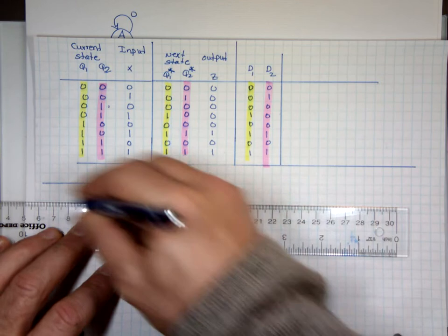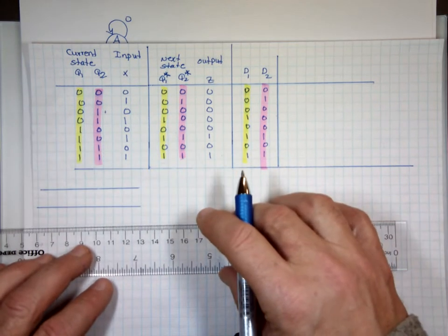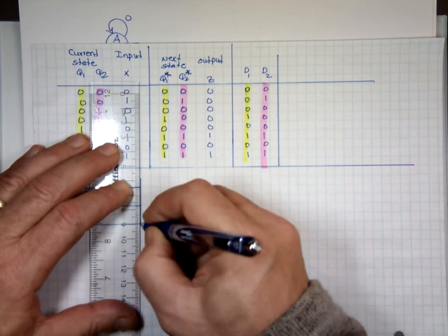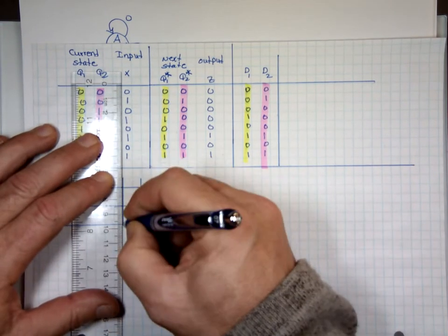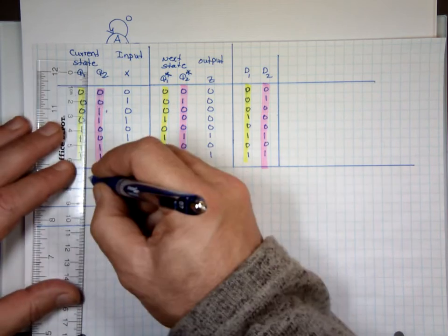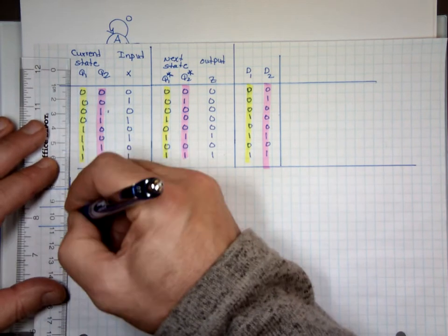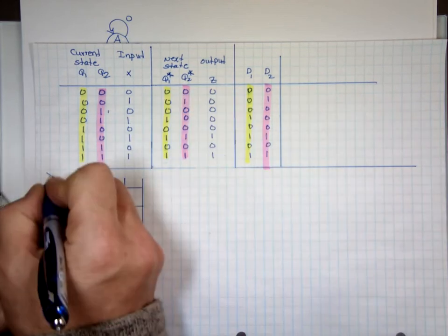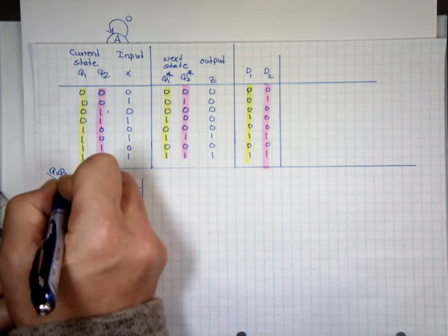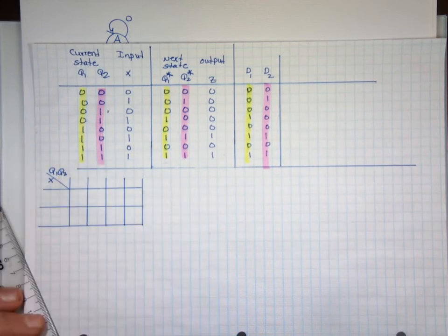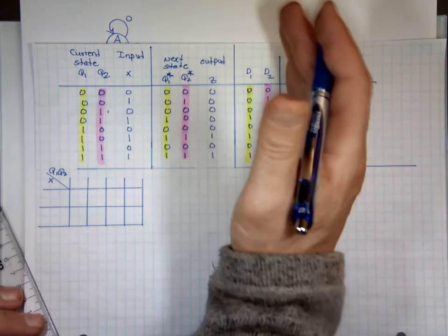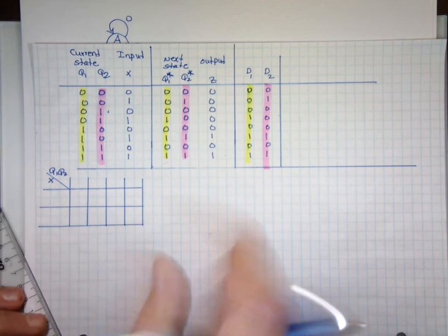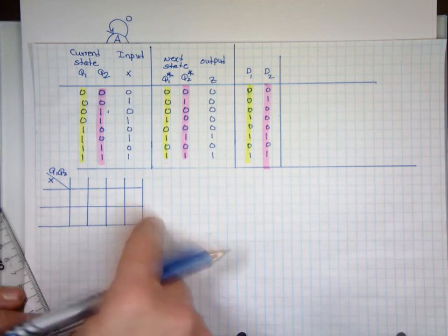Question? No? D and T flip-flop are really popular because it makes it quicker. You don't even have to look at the excitation table. I can mix and match. I can make one of them D and the other one T. You're going to see me next class, instead of using K-map, I might say, let's have fun with it. Let's go back and use a multiplexer for input. Let's use a decoder. I'll do that next class.